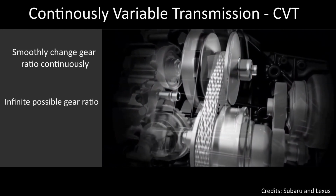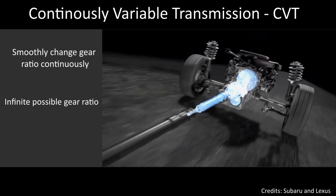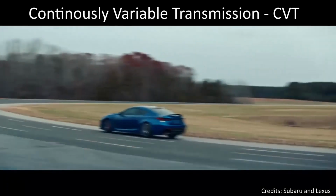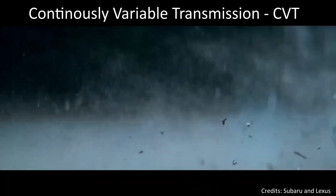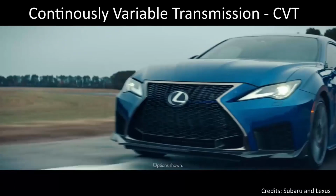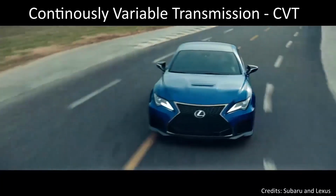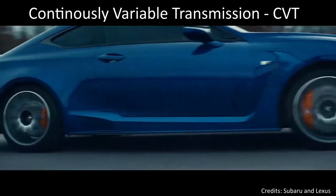Some automotive brands such as Toyota and Lexus have developed an electronically controlled CVT called eCVT. In this system, the transmission has fixed gears, but the ratio of wheel speed to engine speed can be continuously varied by controlling the speed of the third input to a differential, using electrical motor generators.